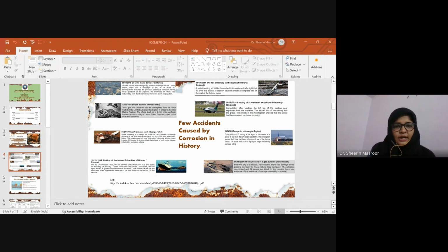Corrosion proceeds in a metal if all the components of a corrosion cell are present at a time: anode, cathode, an electrochemical connection in between, and an electrolyte. The picture depicts a steel pipeline immersed in water, with some part acting as anode and some as cathode. At the anodic site, iron dissociates into Fe2+, leaving electrons, while at the cathodic site, water and oxygen combine with the electrons to form hydroxyl ions. These are taken up by the Fe2+ ions, forming iron(II) hydroxide, which is a kind of rust. This is the basic simplified equation for forming rust.